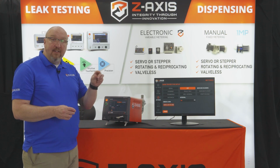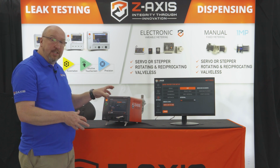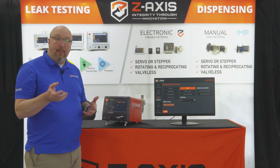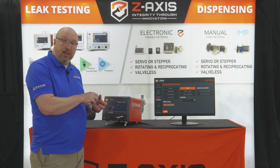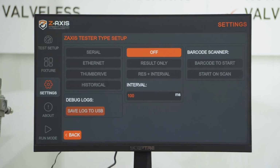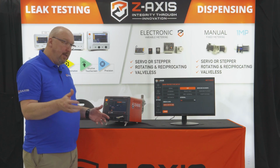I can see the live pressure plot, so I can create some curves and graphs on screens to understand how your part reacts. We can select to use a barcode scanner in the same screen, where we can enable it so that when I scan a barcode, it will append that barcode to the data results that are spit out, whichever of those selections we've chosen. And then I can choose a barcode to start on scan. So the test won't start unless you scanned a barcode to get that data.